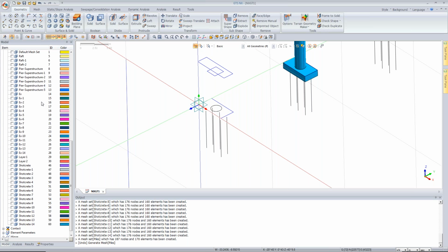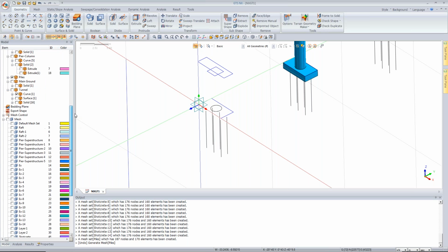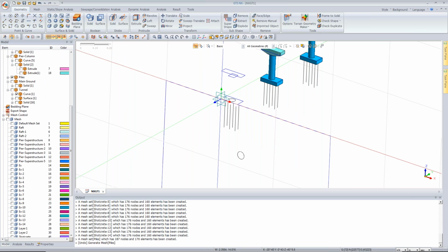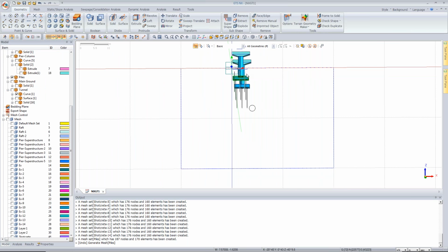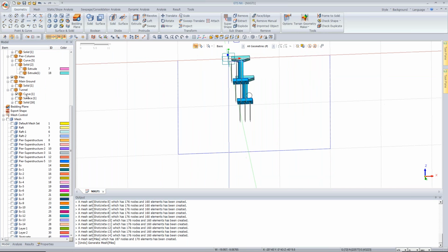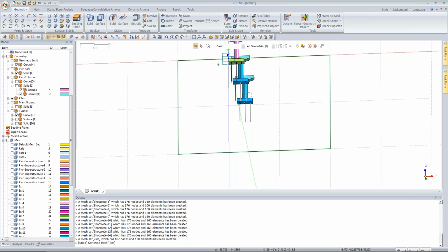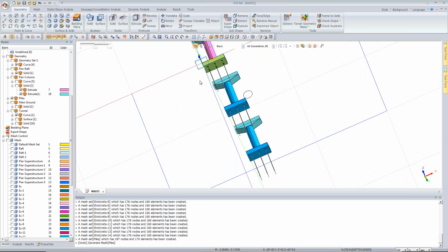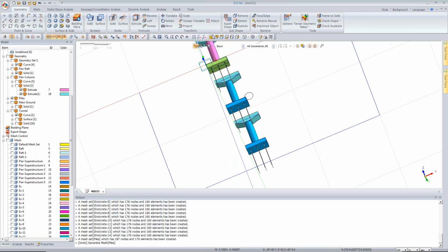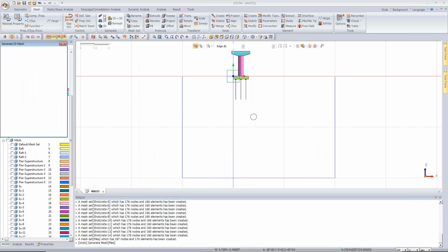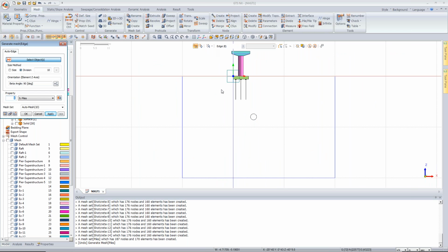Now just to make sure that it's imprinted, we already imprinted it, so I'll just mesh it. If you see at the bottom, I'll activate the solid. So it's already imprinted, so no need to imprint it again. So mesh, 1D mesh, selected the 18 here.